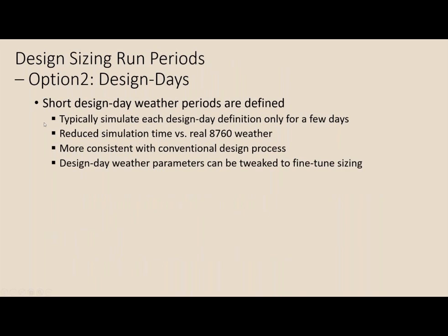So design days are short design day weather periods that are defined to simulate only a few days for a summer design day condition and a winter design day condition. Because of that, you're doing a few days of summer, a few days of winter. Those sizing simulations don't take nearly so much time as doing 8760 weather. It's a little more consistent with the conventional design process too, where designers sizing equipment are typically using design day kinds of weather conditions.